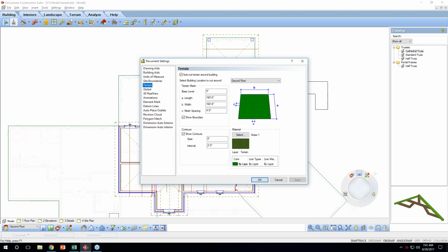Sometimes those field recorders have such a far off range that it was setting that site information way off your screen, and you had to grab it and bring it back. So now as part of the import process, it's going to center it and allow you to pick the center of where you want it to be. That'll be a lot easier for those of you that are importing terrain from an actual field recorder and getting the accurate information right from the field recorder.